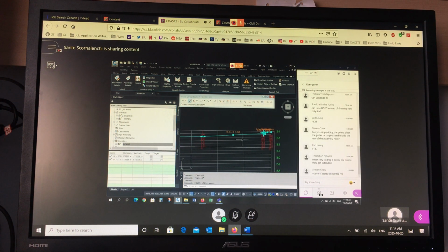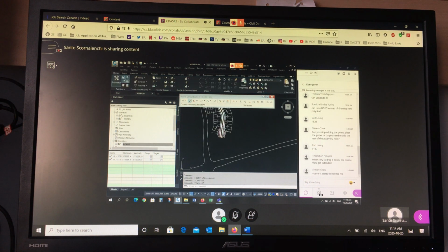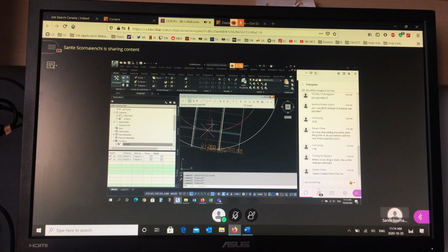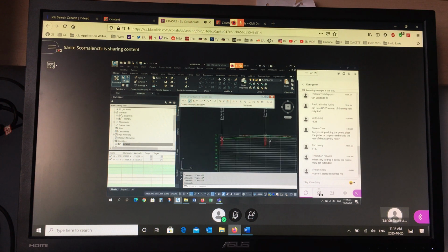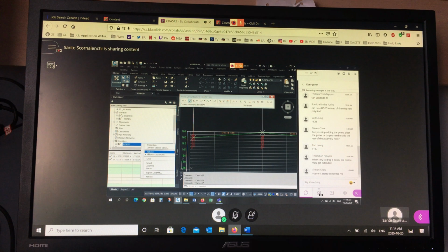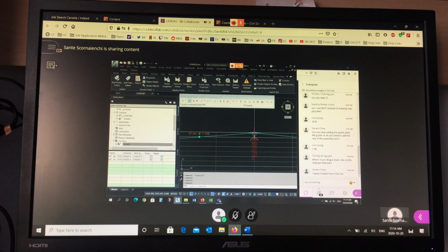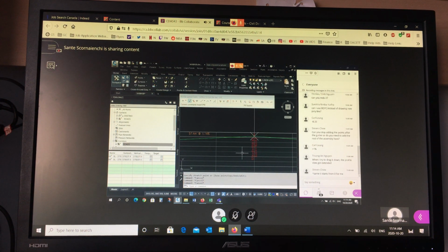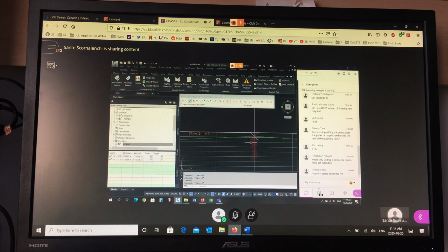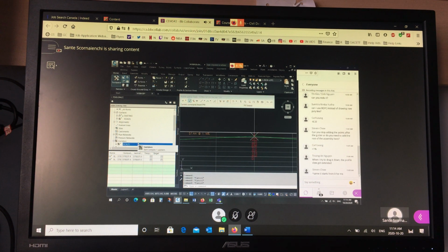So that profile now is defining the corridor, is defining the surface, is giving this point its elevation in the projection, in the profile. Right, so all I have to do is rebuild the corridor, that's the digital equivalent of kicking it so that it behaves properly. Then I say, oh, okay, I made a change, now I need to adjust this design to match. And that works out. So some of the stuff's dynamically linked and some of it isn't, unfortunately. So you have to kind of know that. And when you see something misbehaving, it might be a matter of either making that manual adjustment or rebuilding something that's out of date.